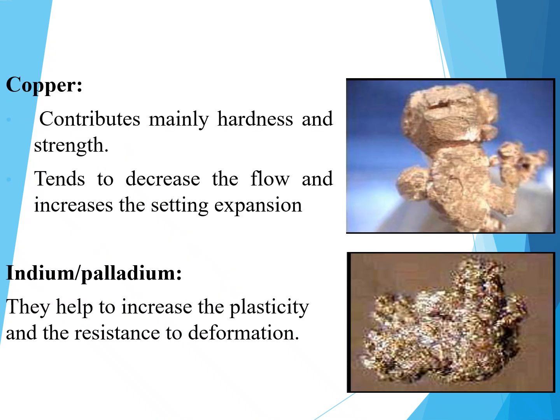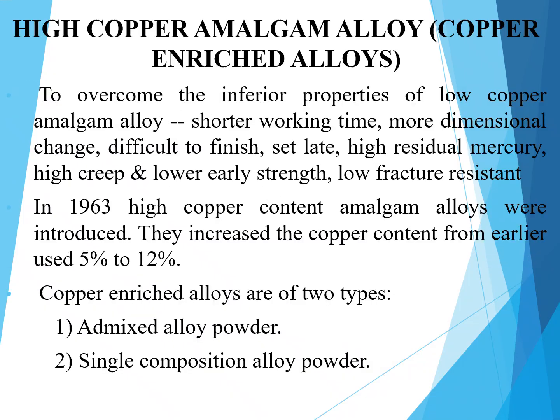The next important component is copper. It contributes mainly to the hardness and the strength. It also tends to decrease the flow and increase the setting expansion. The next component is indium or palladium. They help to increase the plasticity and the resistance to deformation.